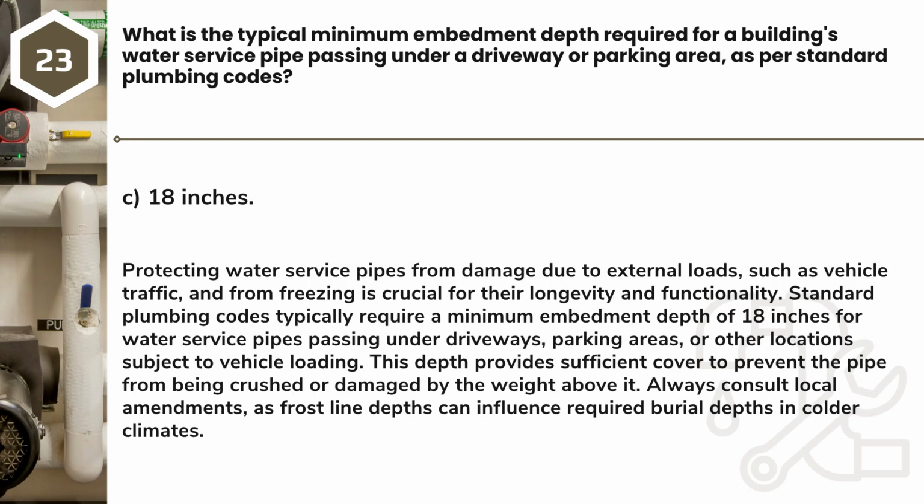Answer: C. 18 inches. Protecting water service pipes from damage due to external loads, such as vehicle traffic, and from freezing is crucial for their longevity and functionality. Standard plumbing codes typically require a minimum embedment depth of 18 inches for water service pipes passing under driveways, parking areas, or other locations subject to vehicle loading. This depth provides sufficient cover to prevent the pipe from being crushed or damaged by the weight above it. Always consult local amendments, as frost line depths can influence required burial depths in colder climates.